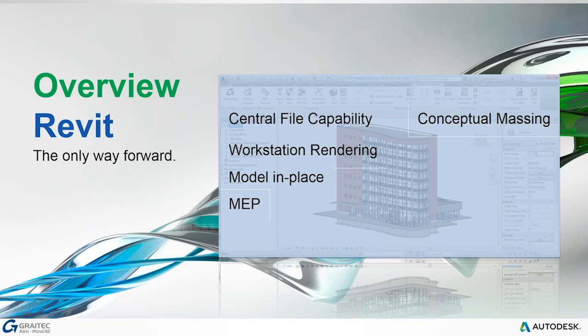The other advantage of using the conceptual massing tool over the likes of SketchUp is as soon as you click on the side of one of these concept masses, you can say, well, make that a wall, make that a curtain wall, make this an actual floor. What kind of floor? Make that a roof. What kind of roof? And it will just make it for you. If you're using SketchUp and then bringing your SketchUp model in, you end up having to effectively use it as a tracing element and you're redrawing everything. So if you do your concept massing inside of Revit rather than using SketchUp, it just leads to a much smoother and quicker workflow. And Revit LT cannot do conceptual massing. Okay.